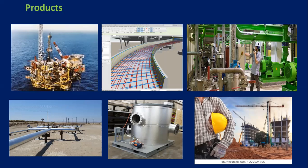Let's say I will give you an example of road. First of all, you have to survey, then you have to do clearing and grubbing, like earthwork, then you have to put aggregate base course, then you go for asphalt, then road furniture works. These are the development stages for the road. Okay. So in the same way you will go for any other product in your industry. So this is the product oriented knowledge, specifically linked up with that product, what standards you have to follow and what are the stages to develop that product.